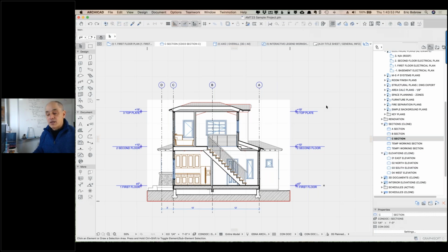It's actually, even in this case for construction document purposes, it's not got the shading. It's just got line work there. And it probably also has some other layers, like the terrain was added, that layer. So you want to use the view map to navigate around so that you have a predictable destination to work on a drawing or work on your model with certain things showing and certain things not.